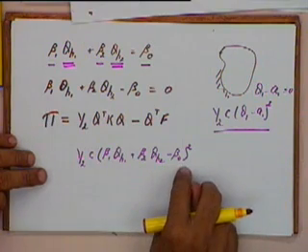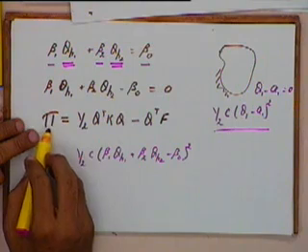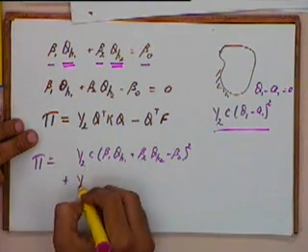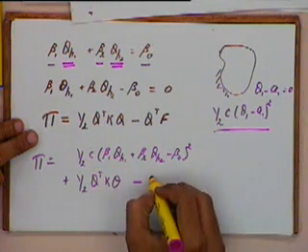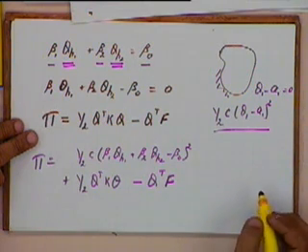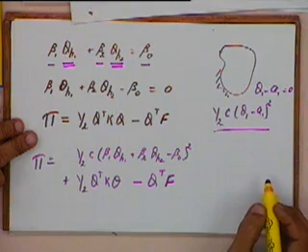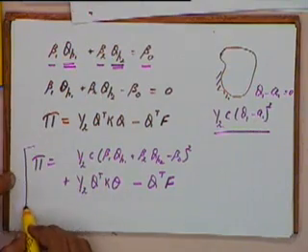This is a potential energy penalty that we will give to this potential energy expression. So we will get pi to be equal to this plus half of Q transpose KQ minus Q transpose F. With this penalty our total potential energy of the system would become this.